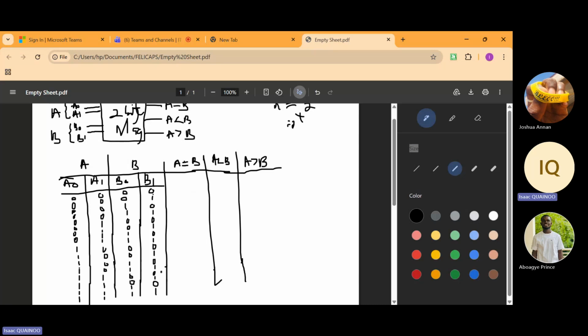So this is how to represent our input combinations. We start from the right side. The right side is just going to be 0, 1, 0, 1, 0, 1. The one before that is going to be 0, 0, 1, 1, 0. The one before that is going to be 4 zeros, 4 ones, 4 zeros, 4 ones, then 8 zeros, 8 ones, etc.